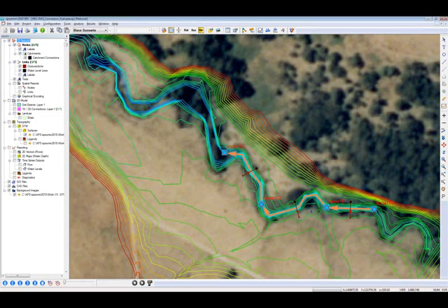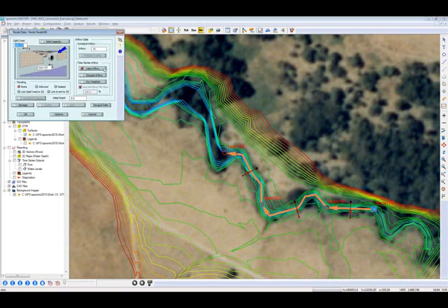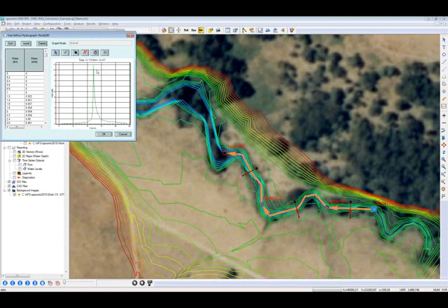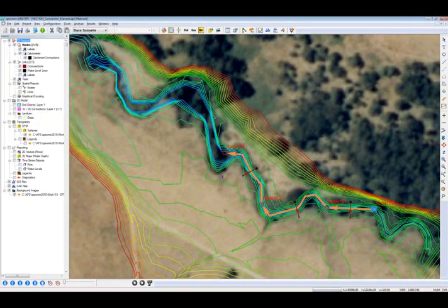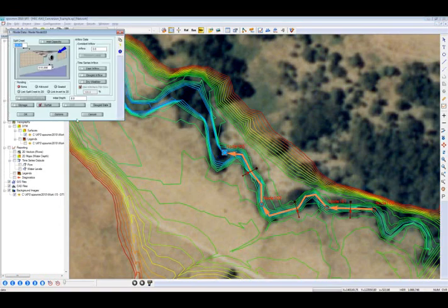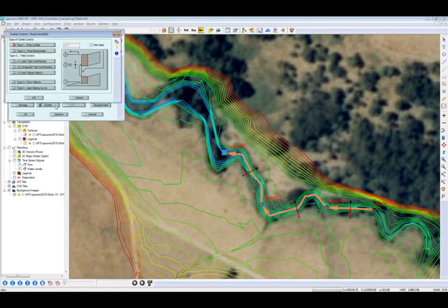And so from here we could run our model. There's a few things which I previously had set up. I set this node to have the inflow hydrograph. As you can see here, I have my inflow hydrograph at the upstream extent, and at the tail of the model I have an outfall. There's a number of outfalls you can use in XP. I've used a normal depth for this demonstration, free outfall.